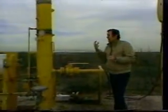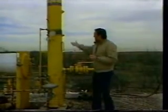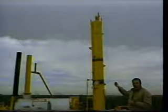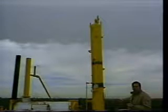The next and final stop for the gas before it reaches the pipeline is here, the gas dehydrator, where the water vapor entrained in the gas is taken out of it. The gas comes in here and bubbles up through trays in this column. On the trays is glycol, which removes the water vapor from the gas. The gas then comes out the top and goes on to the point of sale.